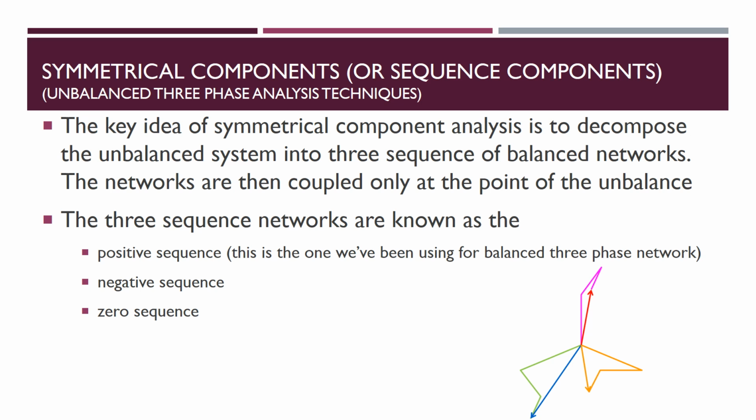This is the key idea of these kinds of techniques. So as I said, unsymmetrical, that means an unbalanced system, is going to be decomposed into balanced components, the symmetrical components, in this way: the positive sequence, the negative sequence, and the zero sequence.